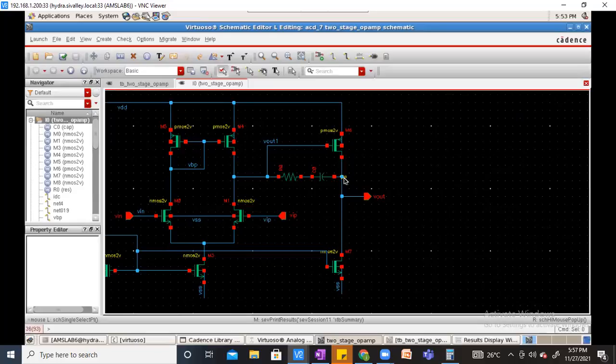You're getting my point? Yes, because I'm trying to correlate, like in the theory we studied, suppose in the network system we have a loop that is going back to the input, but here we have differential input. Suppose the gain will also be divided by that loop feedback factor. Yeah. And in our case, the loop feedback factor is 1, so our gain is 1.